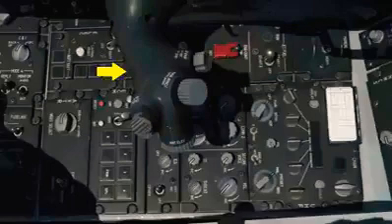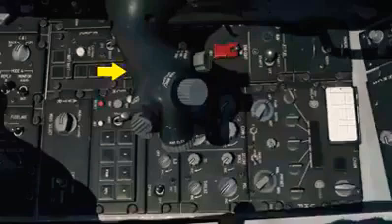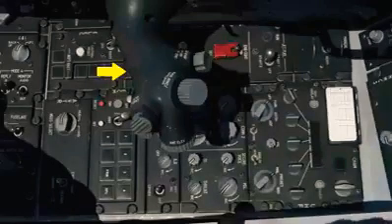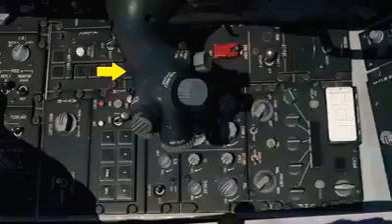The throttle moves in an arc with aft and forward providing thrust. Fully aft, the throttle is in the off position, but then moves to idle when we move forward over the hump. Moving the throttle forward over the next hump engages dry military thrust. Moving over that hump then engages the afterburner. The throttle is one element of the hands-on throttle and stick or HOTAS control system.